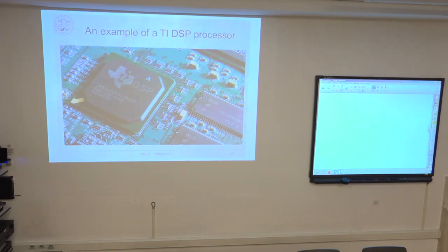And this DSP does the time-intensive, mathematically intensive computation. So your ARM does not have to bother with the problem of signal processing. It does only the fancy things, the operating system, your application, and so on. But real-time audio encoding, decoding, video encoding, decoding, are performed on these DSPs.